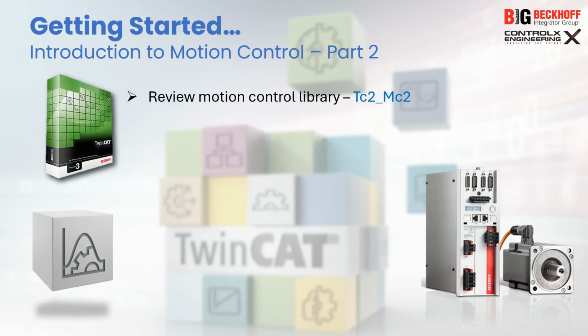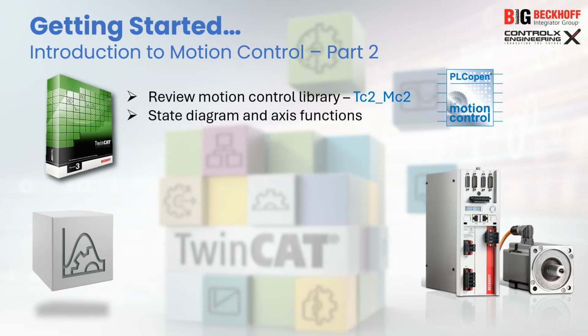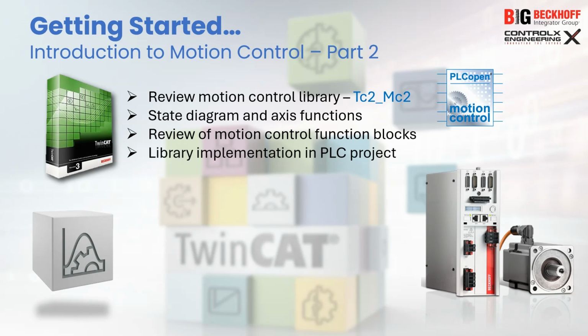Today we'll learn how to control this axis from the PLC using a PLCopen-compliant motion control library called TC2MC2. We'll look at the axis operational state diagram, and we'll review some of the most important axis control function blocks. We'll create a new PLC project and implement the library to control the axis programmatically. Finally, we'll run this axis from the PLC using the motion control function blocks in various configurations using both position and velocity controllers. So let's get started.